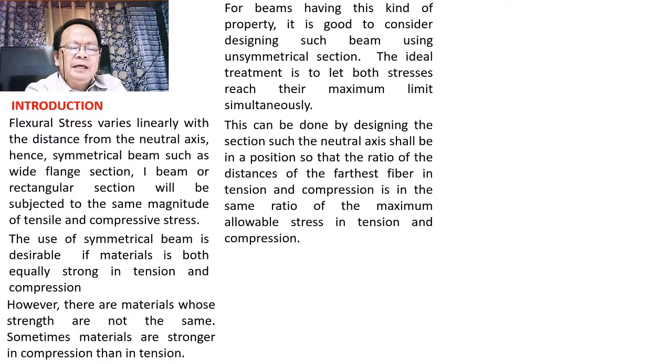We shall be designing such that the neutral axis, itong neutral axis dito po, will be at a position so that the ratio of the distance of the fiber subjected to tension and compression shall be equal to the ratio of the allowable stresses in tension and in compression. So if we shall be able to make it that way, then we shall be able to let their maximum stresses reach at the same time. And hence our design, bagamat yung ating section is unsymmetrical, will be considered to be economical.